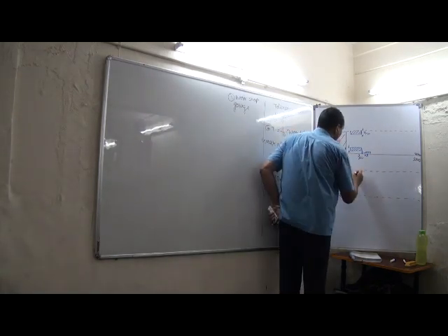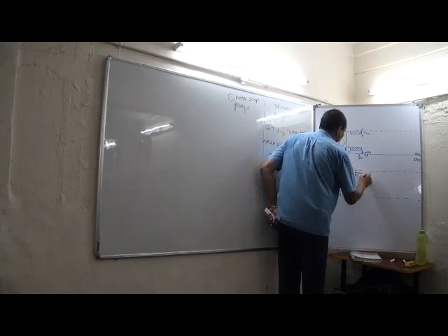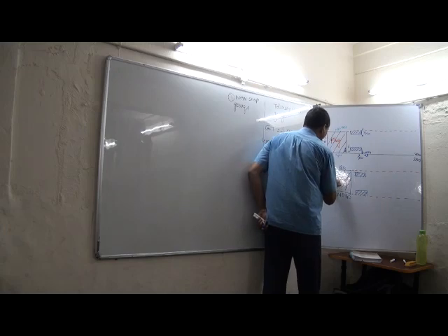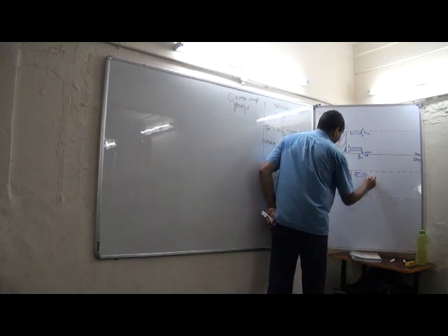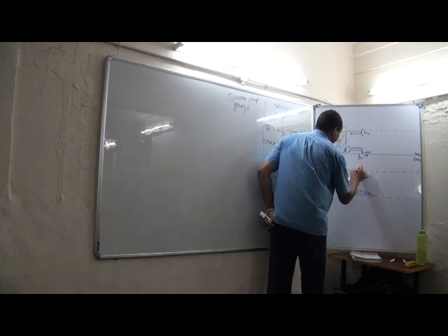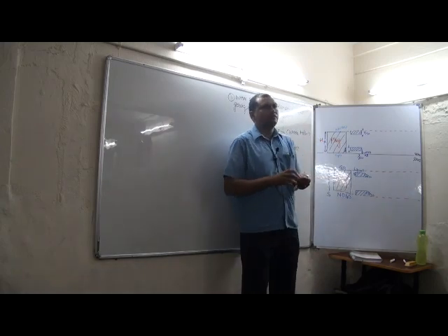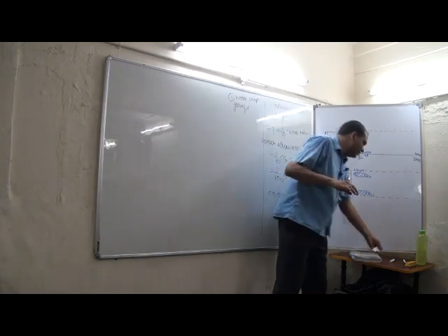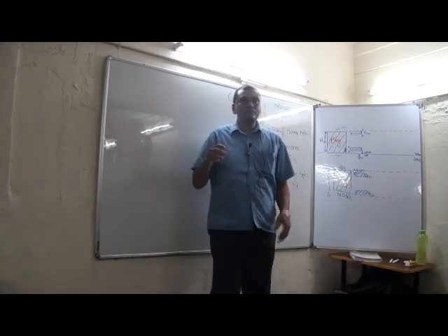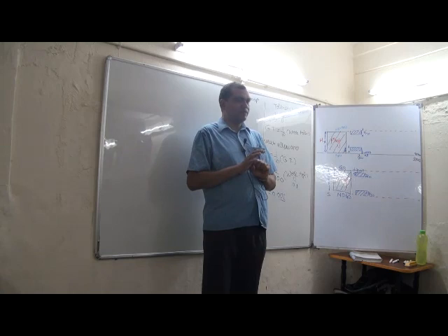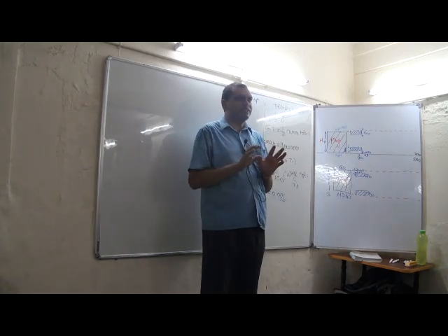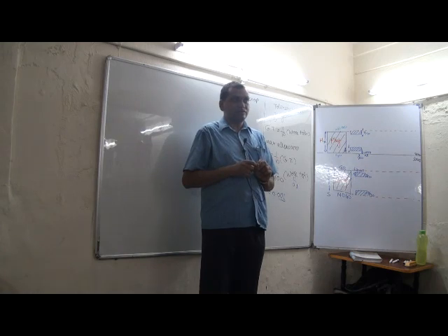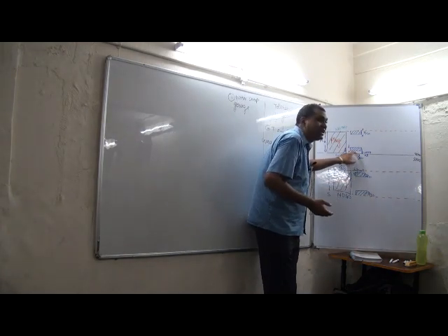And the same thing we can do here for the ring. This is go, and this is no go. Suppose this is Y. This will be Y by 10, this will be Y by 10, and this will be Y by 100. Is everybody following that? Because the philosophy of the workshop department is that we will not produce anything defective. So due to this philosophy, tolerances are towards the work tolerance, and depending upon the work tolerance, we will give the wear allowance or not.